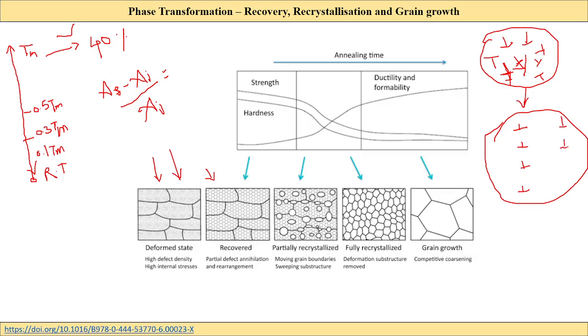You can see here, before, there is a random distribution of more entangled dislocations. Now there is no entanglement of dislocations. Here we can see the perfect arrangement of dislocations, and if we have edge dislocations, they arrange in an array, and more or less they form low angle grain boundaries, right? You know the low angle grain boundaries are accommodated by the array of dislocations at the interface, right?